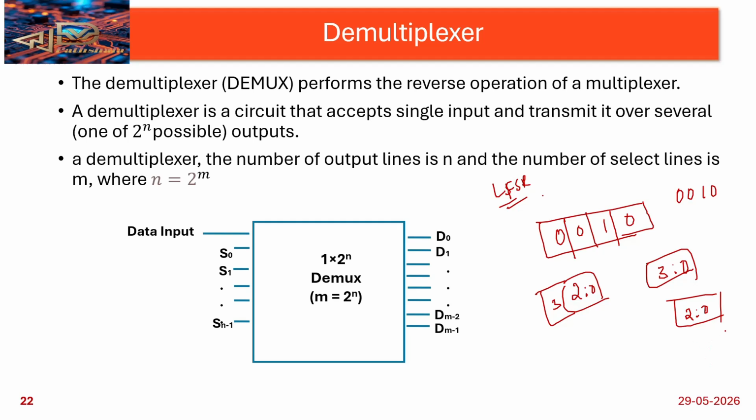Then we take the first bit and the third bit as the feedback bit. For the feedback, we do an exclusive OR operation on the first bit and the last bit. Why exclusive OR? Exclusive OR gives only a 1-bit change. Every time we get a 1-bit change, that's why random patterns are generated.